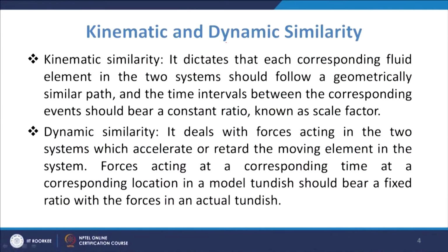Now, the next type of similarity is the kinematic similarity. Kinematic similarity indicates that each corresponding fluid element in the two systems should follow a geometrically similar path, and the time interval between the corresponding events should be at a constant ratio, that is your scale factor. So, that is your kinematic similarity.